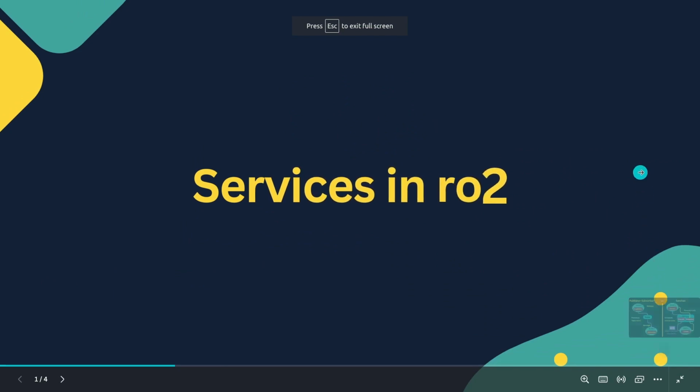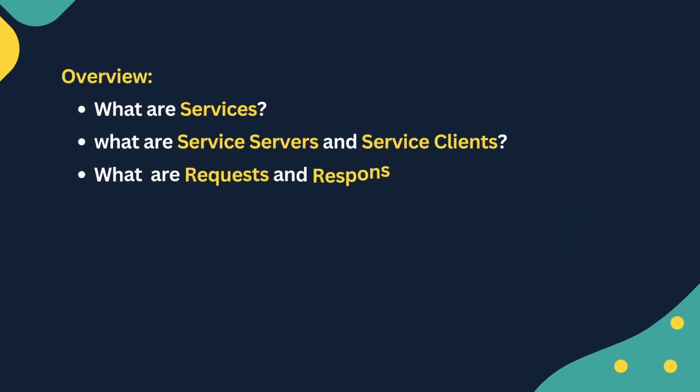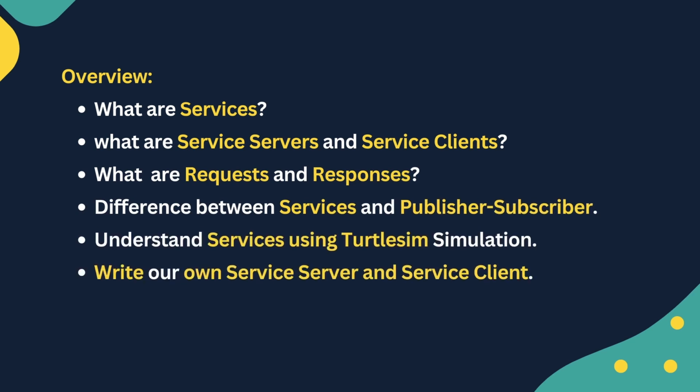Today we will understand services in ROS. Particularly in this video, we will be discussing what are services, what are service servers and service clients, what are requests and responses, and what is the difference between services and publisher subscriber, and we will understand services using a Turtlesim simulation package with an example, and then we will write our own service server and service clients.